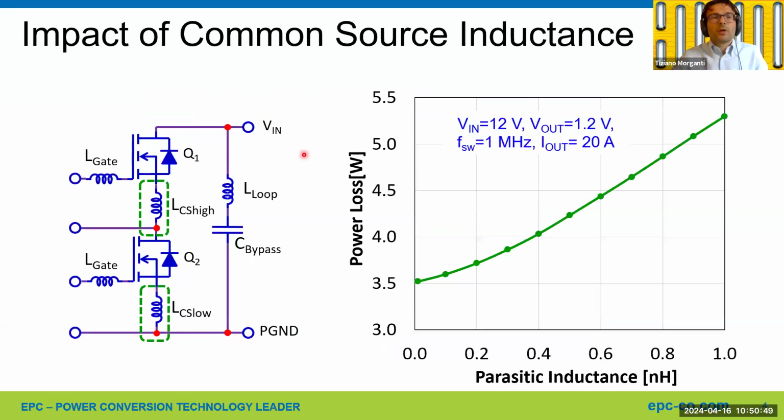Okay, let's consider that you need to turn on Q1. So the gate is at 0 volts. The gate driver transitions to 5 volts. The device Q1 moves from 0 amps current to higher current. So the current in the device is increasing.